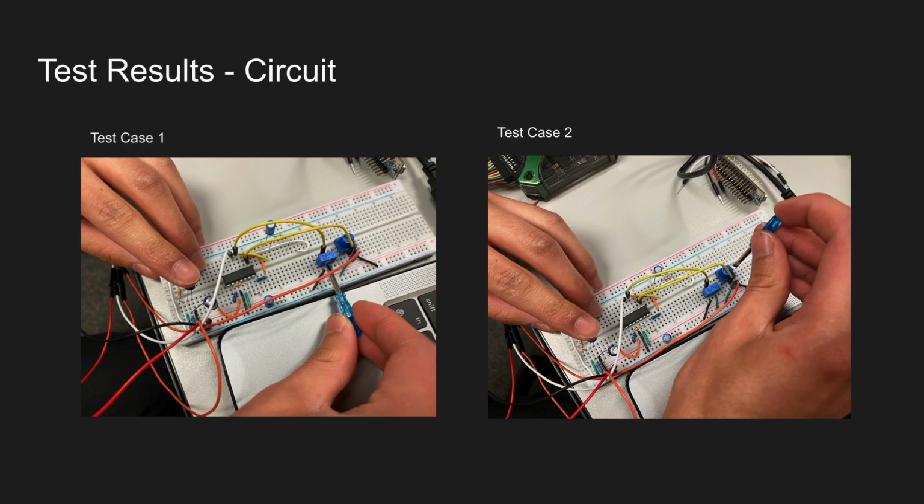We tested different kinds of gains for the op-amp to shorten the peaks, and also applied a DC input to the last positive input of our op-amp to raise the output voltage. This was to move the voltage above 0 volts, but still be below 3 volts so that our STM board could read the results. Now, the peak detector algorithm was not tested much, because it was a little bit more complex than anticipated, and we were not able to test that.